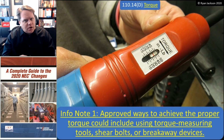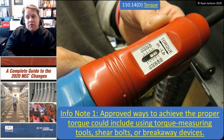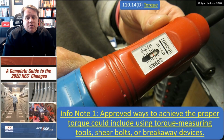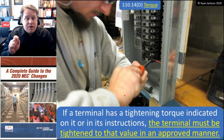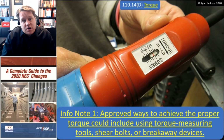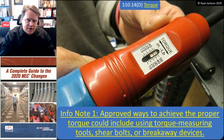So what they did in the 2020 is they said, look, do it in some sort of approved method, because measuring it with a properly calibrated tool is not the only way it can be done. Now, the note says approved ways to achieve the proper torque could include using torque measuring tools, and that's what we have here in the photograph. That is the torque measuring screwdriver that the individual in the prior photograph was using to tighten down that circuit breaker. That is a torque measuring screwdriver, and that would be a great way to check tightness. But we could also use things like a shear bolt or a breakaway device.